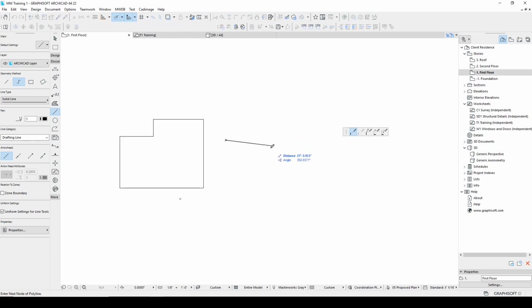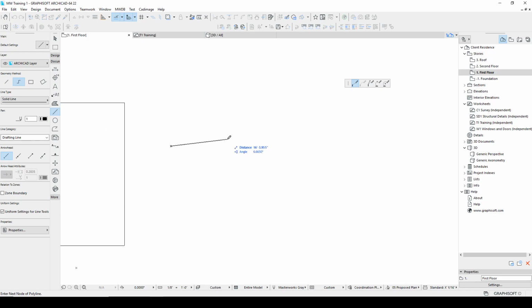So now they're turned off, and you see it's not giving me any aids, and it's not snapping to a 0 point. So this is how ArchiCAD used to work. So I learned to work without them. I think it's a great feature, and I encourage you to use it. But I'll show you an alternate method, and sometimes it has its advantages.